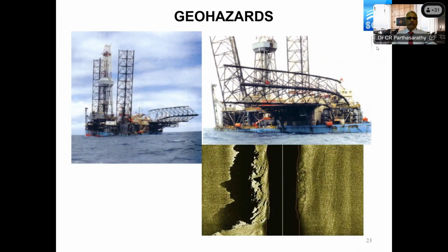So the geohazards can lead to distress of the legs when you have a rock outcrop, when you are pulling the rig to the locations. If it is lowered to the seabed to pin, we do the soft pin in a soft place. Perhaps the soft place is no problem, but you have rock layers, where the bottom of the spud cans is touching the rock layers and you're still pulling the hull, and then probably it will bend and you'll see the distress in the jack-up rigs.